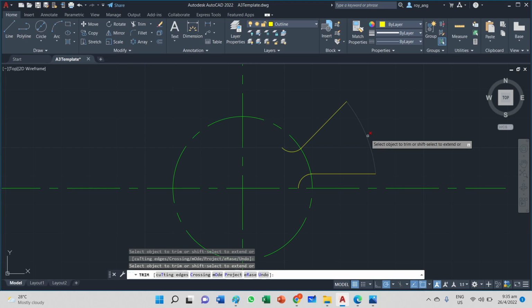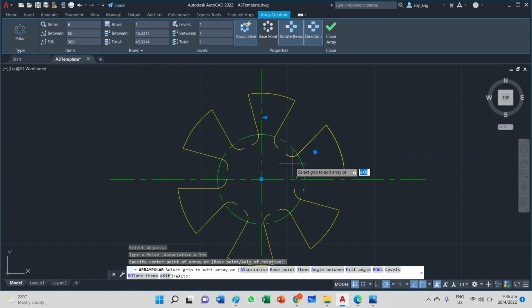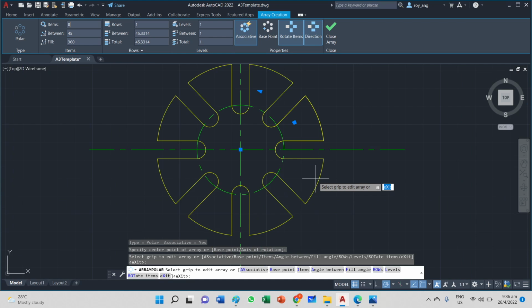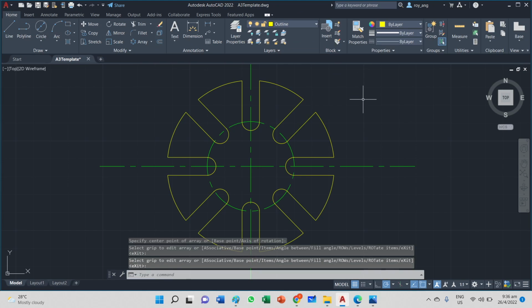And what you want to do is rotate it or do the polar array. The one that you want to polar array would be this segment, this 1, 2, 3, 4, 5. Okay, and once those are selected, you can right click to accept the selection. You will rotate about this center. Okay, and you actually have 8 instead of 6, so you write 8. Okay, rotated about 360 degrees. So you see you have all this out. You click OK, right?